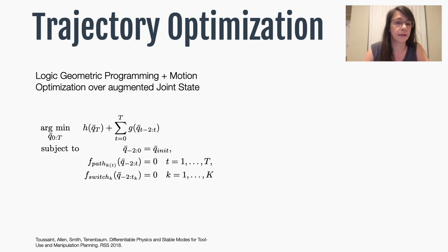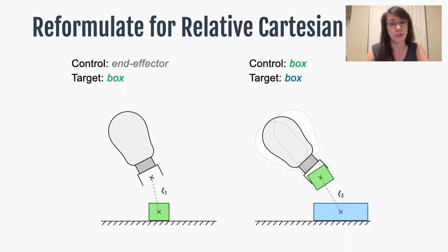And the problem with the joint angles is actually that whatever joint trajectory is basically output, once you have this optimization problem solved, becomes invalid as soon as the environment changes and you have to run this entire optimization again. So how do we have a way to combine a symbolic plan with a trajectory optimization plan that is actually adaptive in case the environment changes? That was the question we were asking.